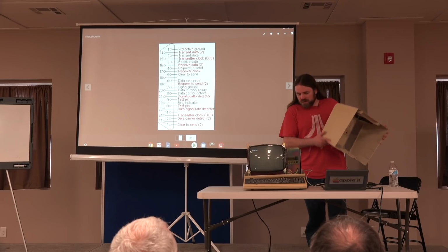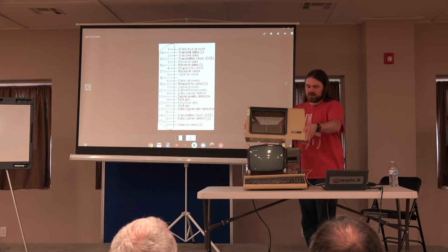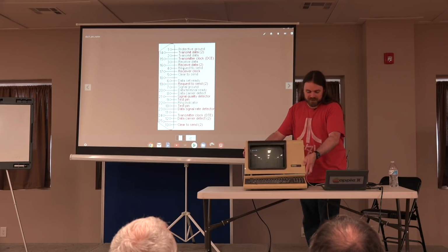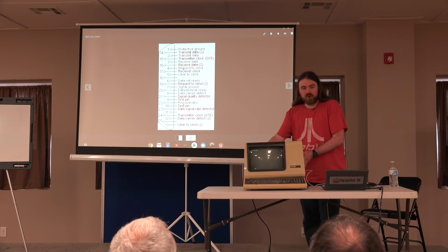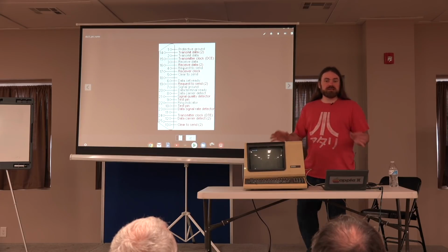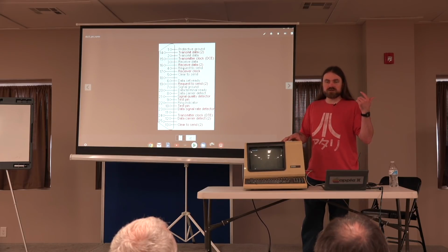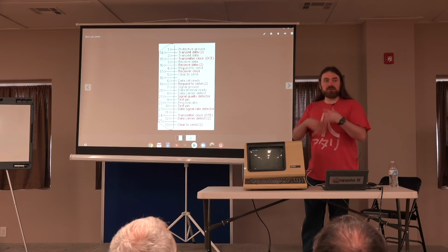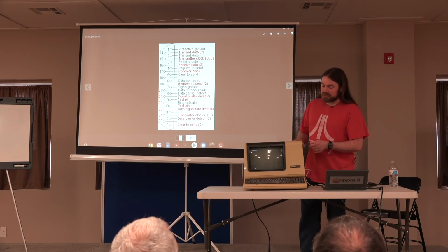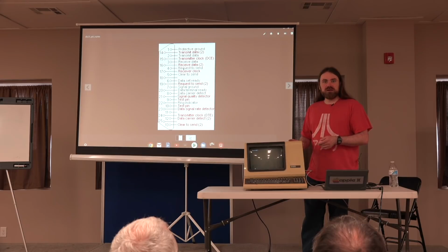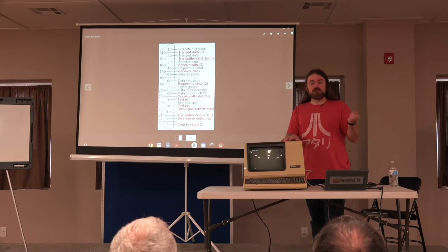I don't remember. Some terminals, like the one on Jason's shirt back there, the ADM3, have no microprocessor whatsoever. It's all TTL logic. There's a 40-pin UART. There's a bunch of basic logic to run through, just handling the screen, and that's it. There's no processor. And so you hear people talk about a dumb terminal versus a smart terminal. The lines start to get blurred. Something like an ADM3A is a dumb terminal. It's very simple. It can do basic cursor position. It has no microprocessor. Can't run any kind of local code.